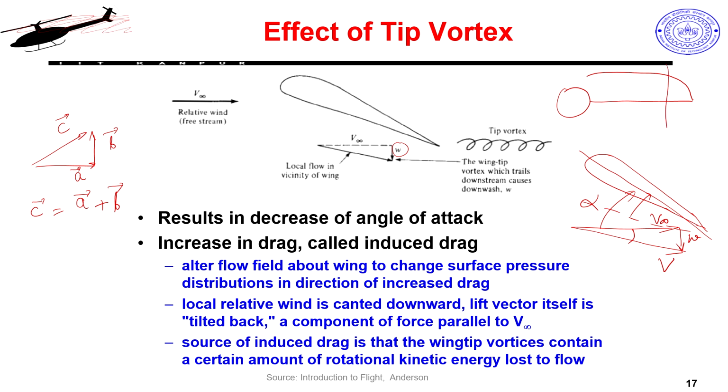So, whenever we want to design an aerial vehicle which we expect to have better aerodynamic characteristics or higher L by D, because finally that is our aim, I would want to have a wing which has less and less of 3D effect. So, can any of you tell me what can be done to reduce this 3D effect? A winglet is fine, but yes, winglet is one way where I have something added to the tip, I modify my tip. If I do not modify my tip, if I have a normal design, what can I do?